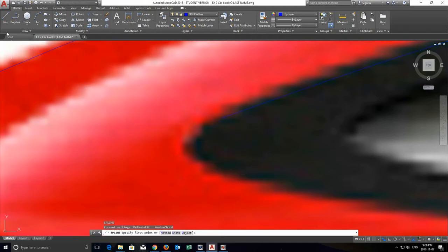If I want to put that corner in here, again, I'm going to start with a spline curve. Now, first of all, I want to start right where this line left off. That's where I'm going to turn on my snap points again, and you'll see I'll snap to an endpoint. Now I'm going to turn those off because I don't want to snap anymore.